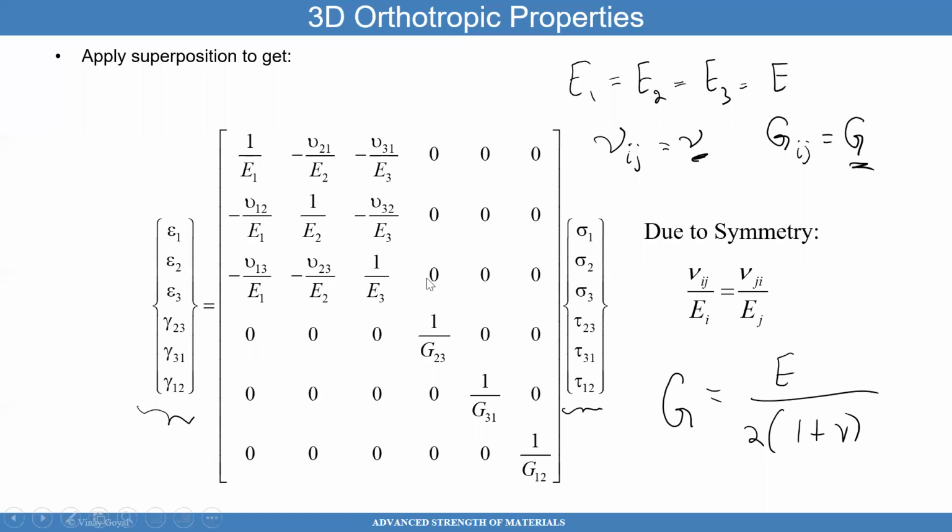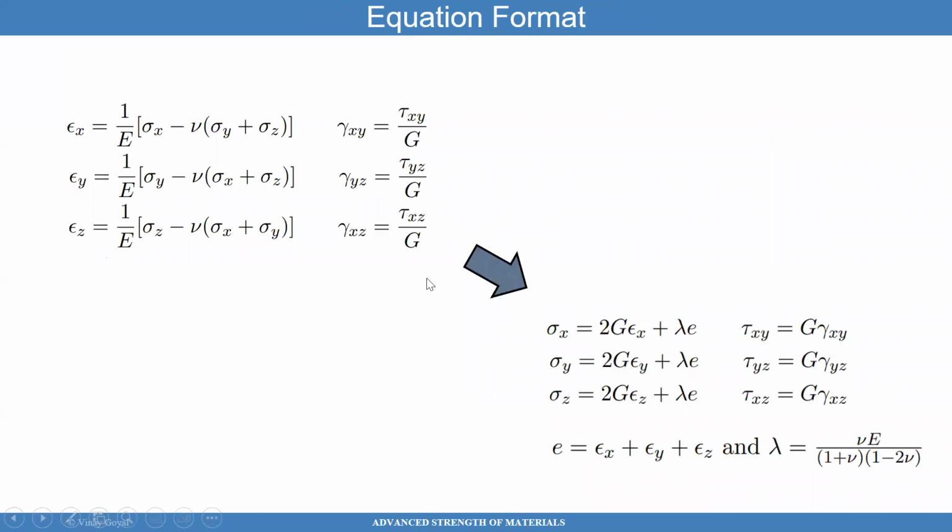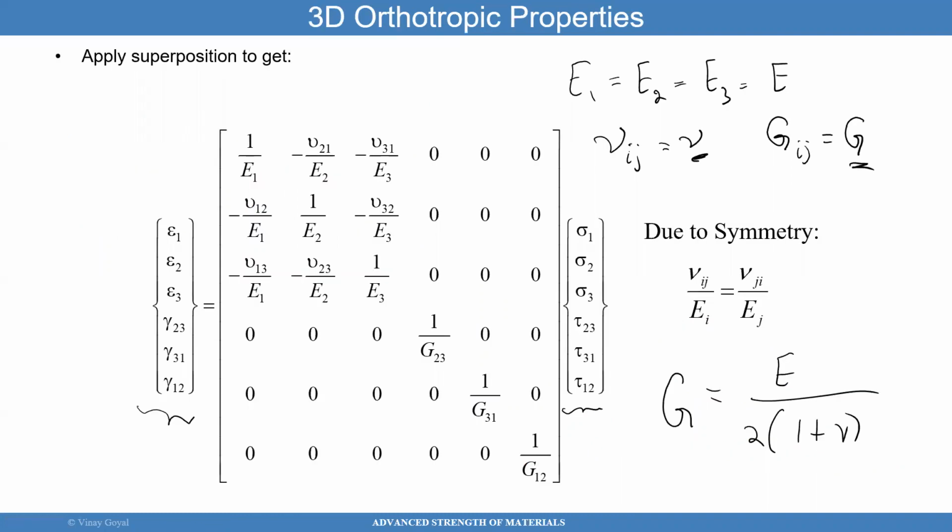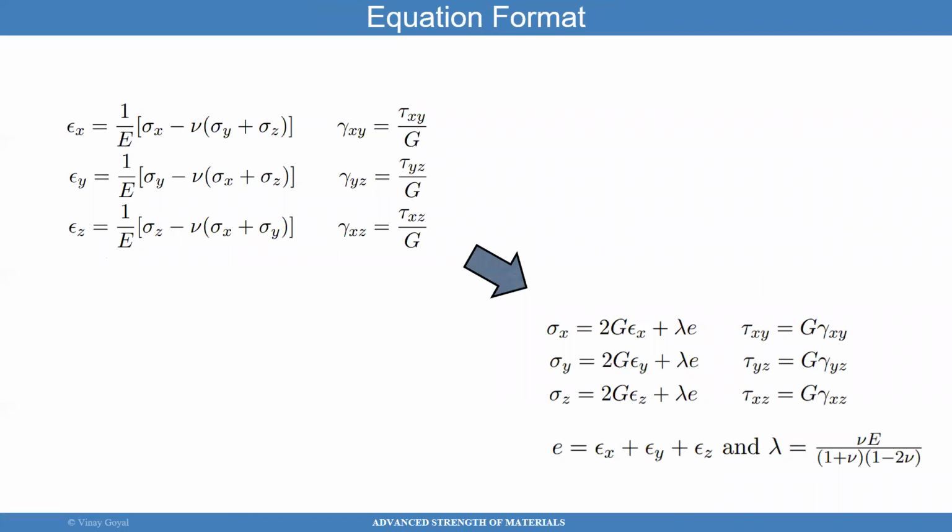So, all right, we'll continue here. I'll write it in equation format. Matrices can be scary to look at, but if I look at isotropic materials, then it looks as simple as that. And you can see that if I apply a load in X only, so then I have sigma XX, and these are 0, and then you get exactly what I discussed earlier. So you can see that works out.